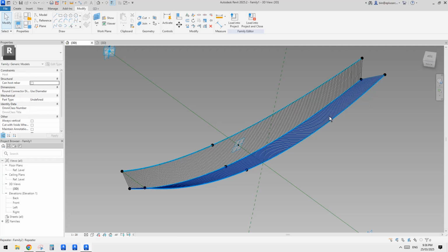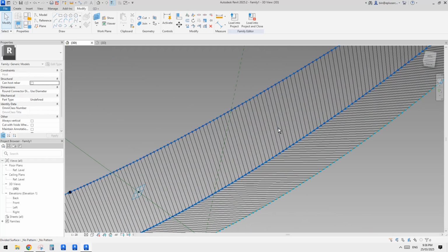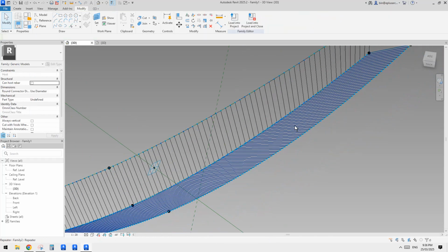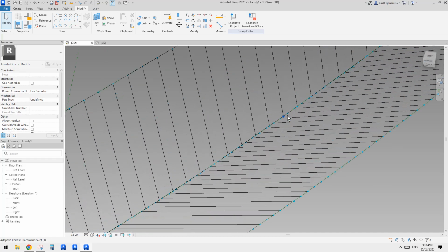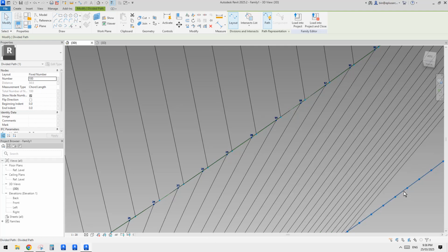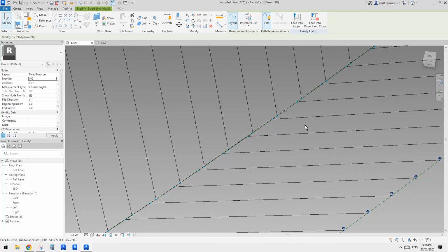Or actually, maybe let's reduce this number a little bit, because I know how slow it can become if we have too many of this adaptive family, right? So I'll change this one to 100 as well, and also we need to change this one to 100. So I think all good.